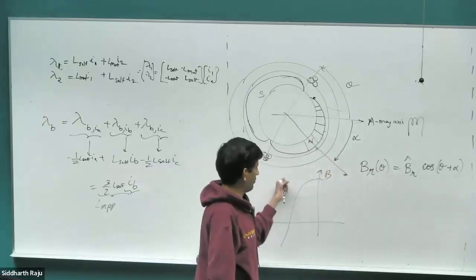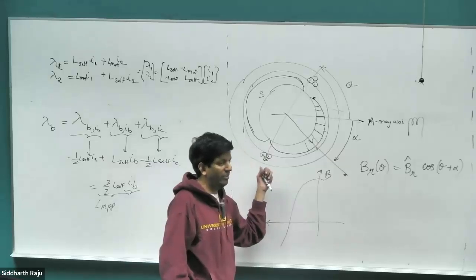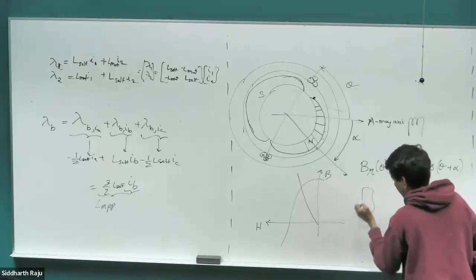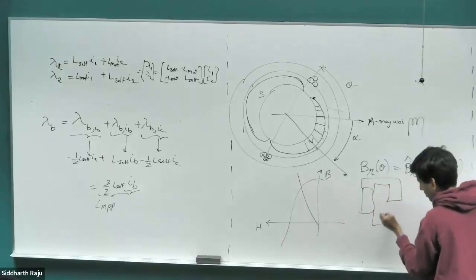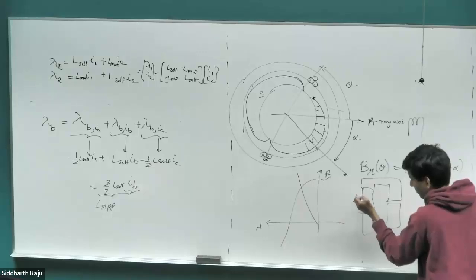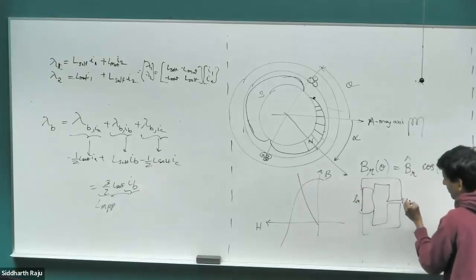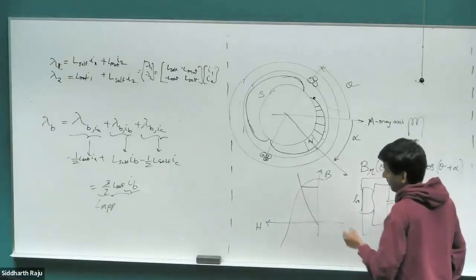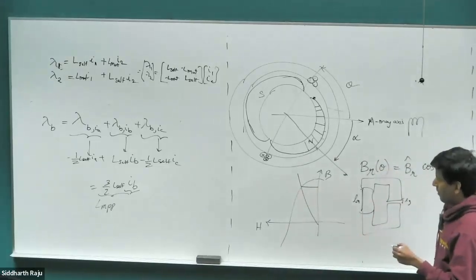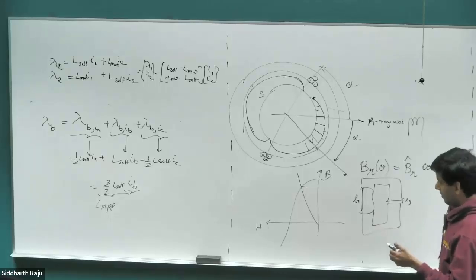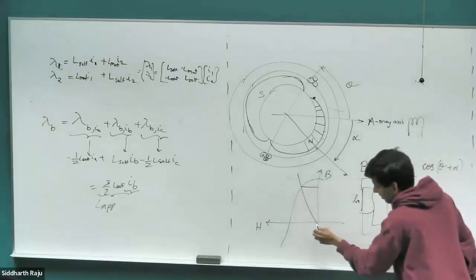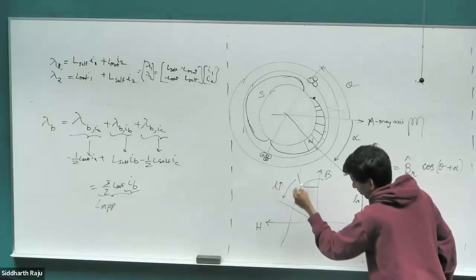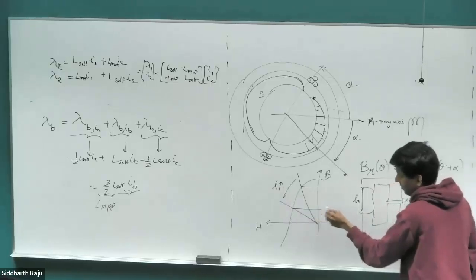Sure. But where it lies on this, the load line, is determined by the ratio of Lg divided by Lm. So we have a load line here. If you had a magnet in an iron core, with Lm the length of the magnet and Lg the length of the air gap, that ratio determines where this load line lays, and that in turn determines what the magnetic field strength of the magnet ends up being. As Lg increases, the load line starts to fall lower and lower, and your field strength starts to reduce.